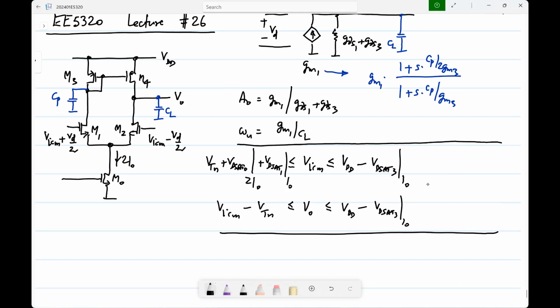Now, of course, in any op-amp circuit, both these limits have to be satisfied. That is, the input common mode voltage must meet the limits on VICM, and the total output voltage must be within the limits on VO. So depending on the kind of circuit you have, one or both could be significant. For instance, in non-inverting amplifier topologies, you also have a significant common mode swing, so the common mode swing limit may also come into the picture, right?